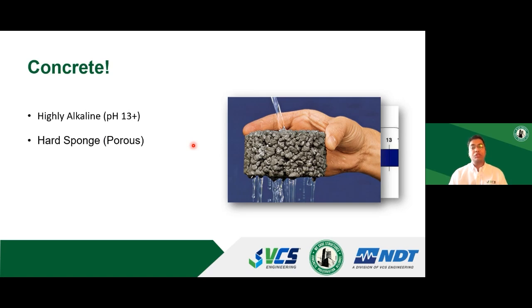If your concrete is exposed to marine exposure, again, the chlorides and moisture will get in. If your concrete is exposed to carbon dioxide or carbon monoxide, which is essentially a lot more acidic, carbon dioxide and carbon monoxide will get in and acidify the concrete. So because of its porous nature, it will absorb a lot of the species that result in corrosion of steel.